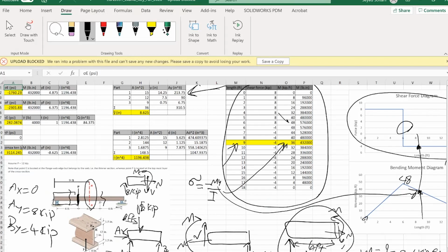In order to save time, I'm just showing you the tabulated values. We need to determine the Y for the centroid of each sub-area, multiply that by the area of that sub-area, add them up, and then divide by the area of the entire cross-section, right? If you do that, the Y position of your centroid would be equal to 8.625 inches, measured from the very bottom of the cross-section.